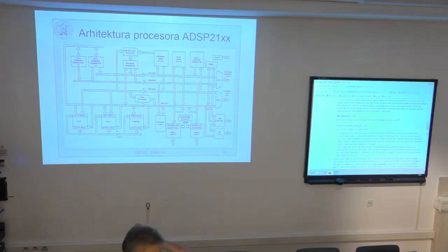But nevertheless, you still have a bottleneck in this case, and the bottleneck is the data throughput. Because if you want to supply input arguments for all 3 units, you cannot do this, because you have only 2 buses, 2 data spaces. You can only fetch 2 arguments, or maybe fetch one and store the other. But if you want to have 3 parallel operations, how can you do this? Because then you have 6 arguments that are needed for these operations. And this would require even more parallel data spaces to be able to fetch all of this data simultaneously.